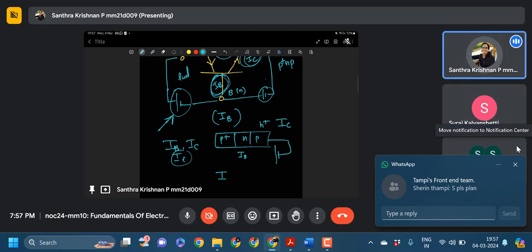This is adding value. It is constant. Though the amount is small, it is contributing to IB. Means you are asking in terms of the equation whether IB matters, or only the alpha value matters. Then only alpha matters. In the ideal case, IB should be zero, but since it is a non-ideal condition, some amount is lost as IB. You can logically equate IB to the loss that is happening because of the unwanted recombination.